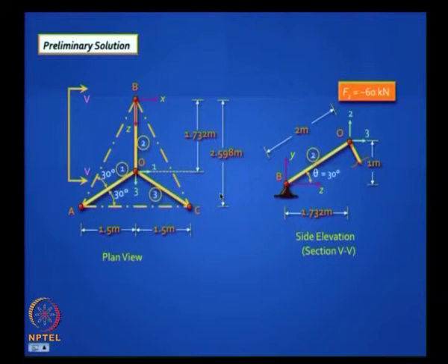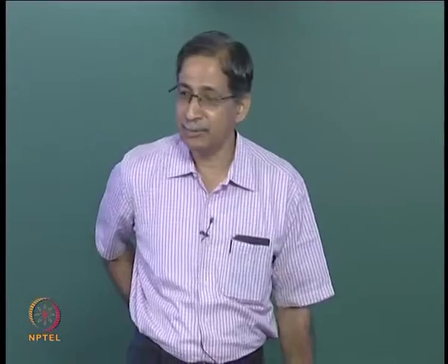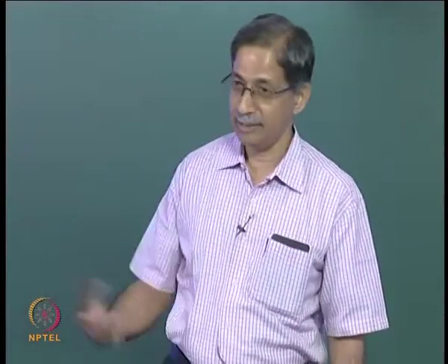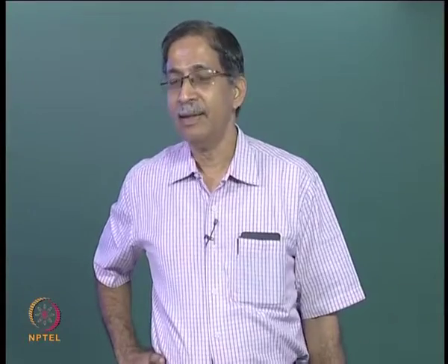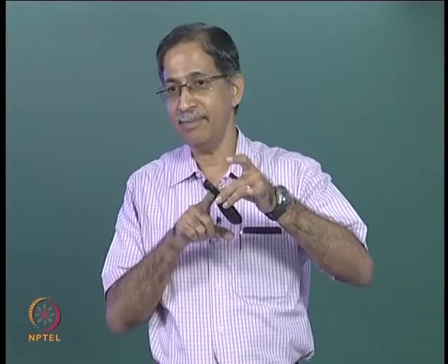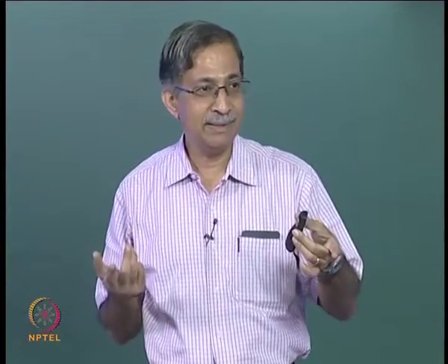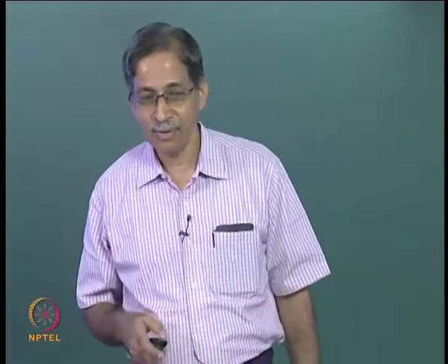That is the first thing you need to do. Now without doing any calculations except extremely simple ones, can you tell me what is the force in each of these legs? Will the forces be equal? Yes. Tell me the value. The total weight is 60. So 60 divided by 3, 20? No sir. Come on. How do you get it? Common sense, how do you get it? The vertical component is 30, so the axial force in each bar must be 40 in each. Is it clear?